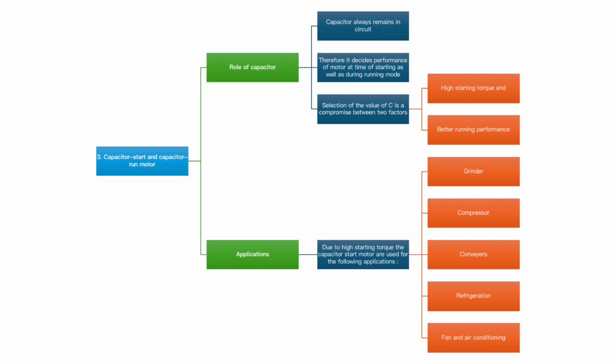During the normal operation, the rated line current is smaller than the starting current. Hence, the capacitive reactance XR should be large. Hence, CR should be small, which is our running capacitor. As motor reaches the synchronous speed, the capacitor Cs is disconnected by the centrifugal switch. The capacitor CR is permanently connected in the circuit and is the run capacitor.